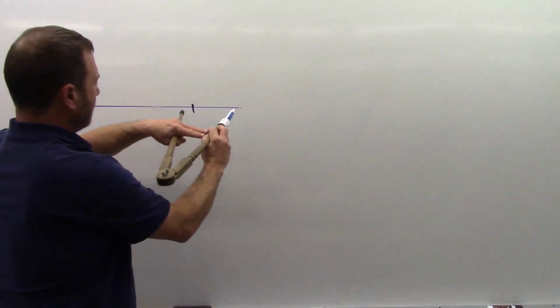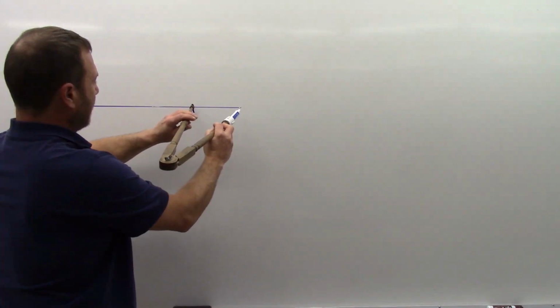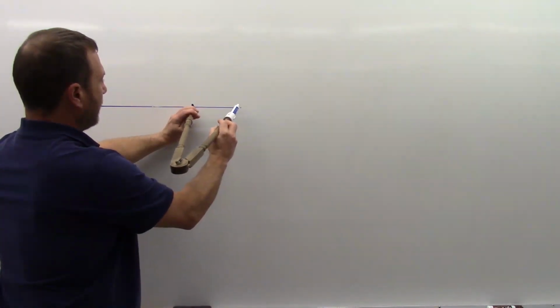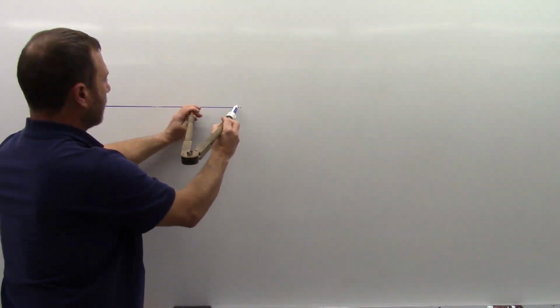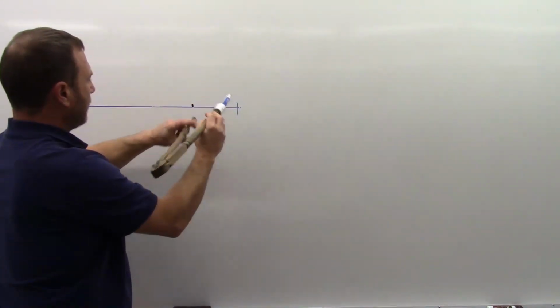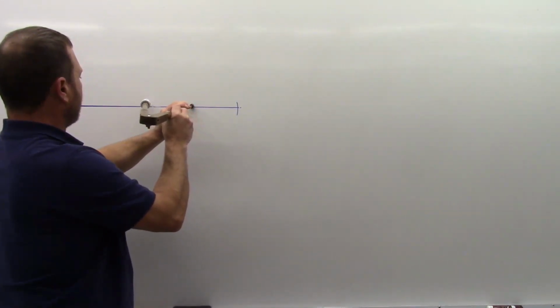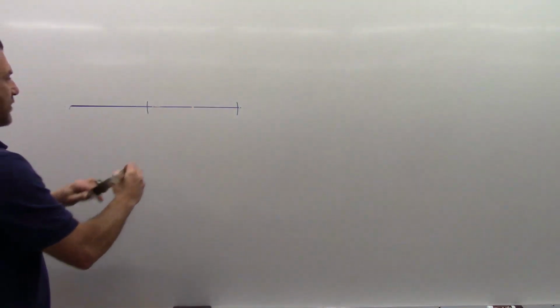The next way we'll look at perpendicular is anywhere along the line. So not necessarily on center of the line. In this case, we're going to take our compass and set it to a distance, and this one is really arbitrary. The distance just has to be something reasonable. I'm going to go just small here because I'm near the end of my line, and what I'm going to do is swing an arc both left and right of my original point.